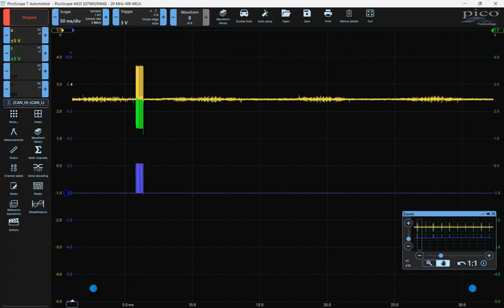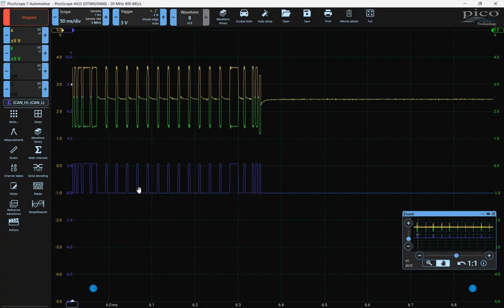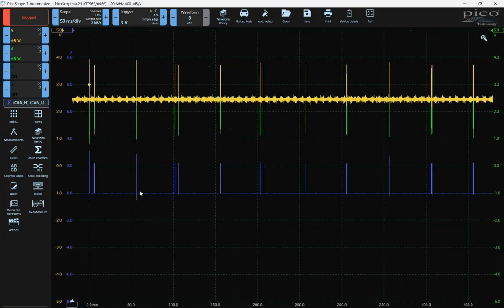So my 0 volt level is somewhere right here on this line. I have a very clean looking signal, regardless of how ugly it might look on the oscilloscope in reference to ground. But because the CAN transceivers reference CAN high minus CAN low, each in reference to ground, and then look at that difference in CAN high and CAN low, that common mode voltage, or that voltage that is induced or placed on both of the wires equally, basically gets zeroed out or negated. But anyways, we can see that I have this small network.